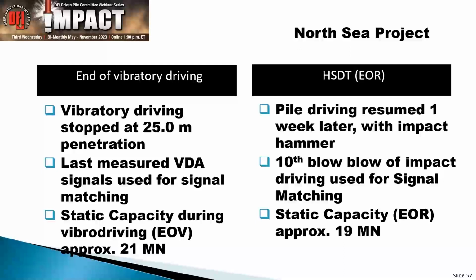First of all, it showed that we can, especially in granular soils, in cohesive soils, in clays, it's still, we don't have as much experience, because most of the time when we drive a pile offshore, it's in sand layers in the sea.